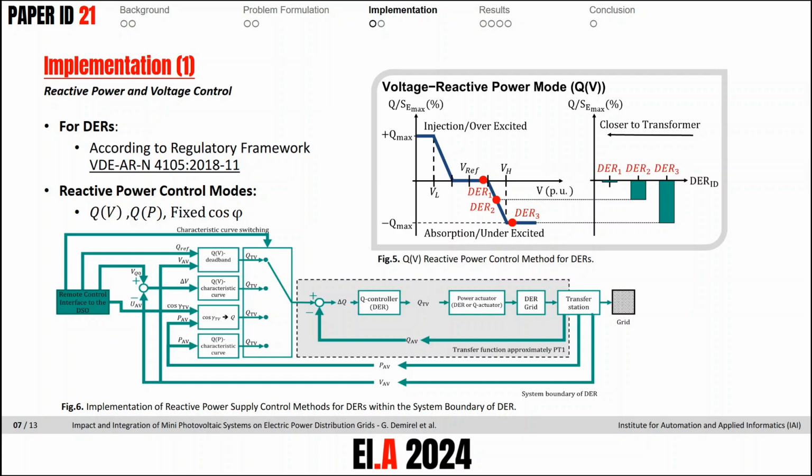The first variable is the active power generated or target value of the DER unit or inverter. The second is the current measurement at the point of common coupling. DSO controls the respective reactive power control mode remotely depending on the method which is used. The desired reactive power is then fed into the grid. A new measurement serves as feedback. The mathematical description is presented in our paper.